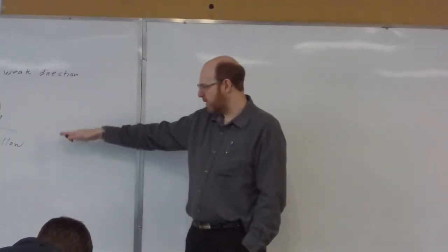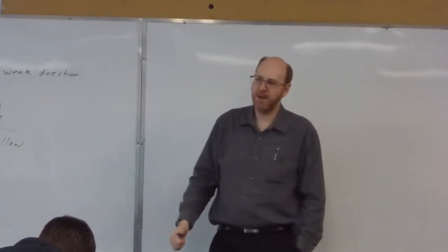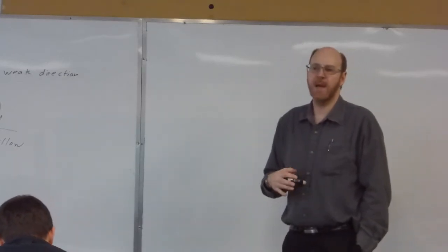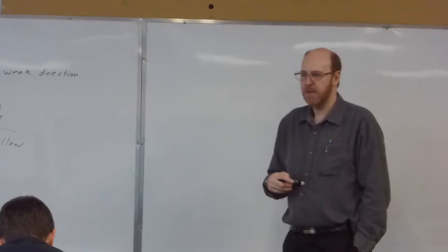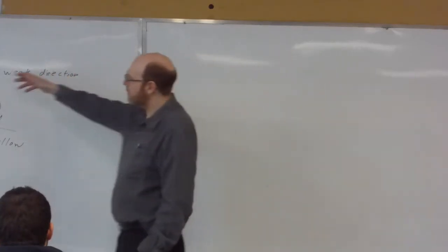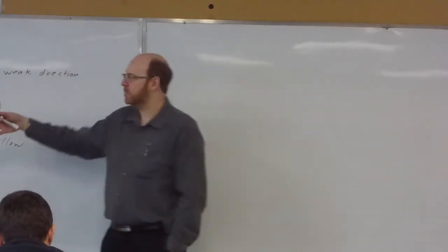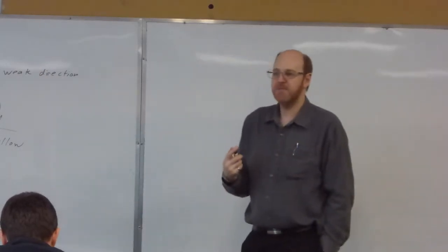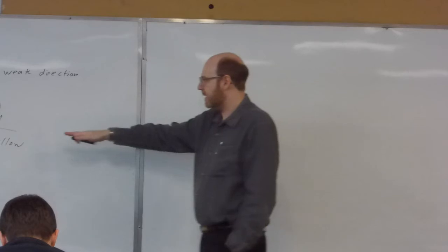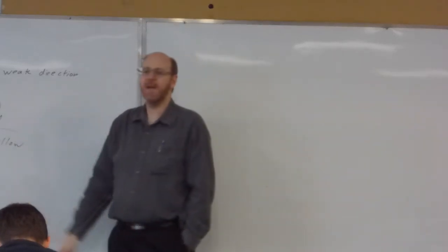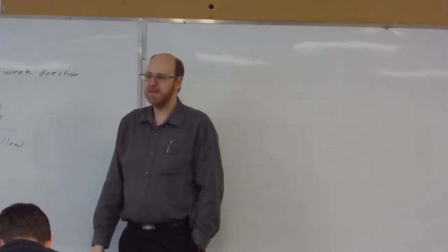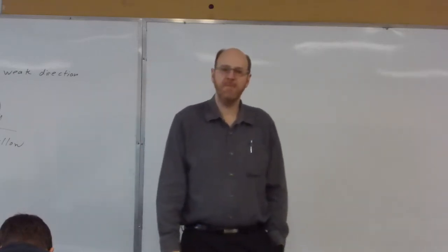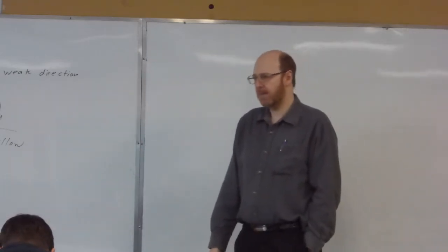Again, notice with our connection details, as we apply our factors of safety, the phi factor is much less than what we're looking at for other design parameters. So for our columns or our beam designs, moments, shear, axial load, there typically we're using a phi factor of 0.9 for steel, whereas when we get to connections, bolts, we're using 0.8.